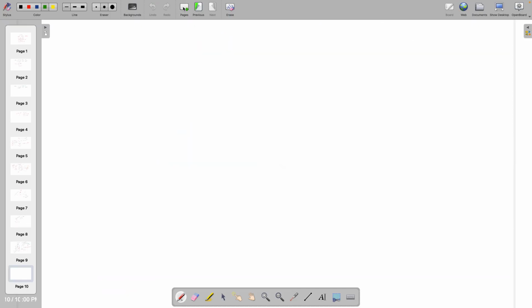So first one was DC. I believe you understand what is DC. So this is a DC source. Let's say its name is Vin, both capital, right? So it's DC. DC requires only one thing. What is the value of this DC value? Again, I'm telling you, if it is a voltage source, you don't have to write down its volt. If it is 1 volt, just write down 1, right? If it is 100 millivolt, write down 100 milli only. So our simulator is intelligent enough, right? So this is the only thing required.